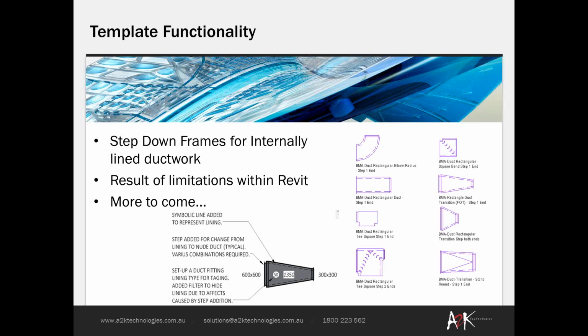Okay. So in conjunction with some of the users involved in the BIM MEP AUS user groups, we've developed these step-down frames that allow you to keep the airway size the same basically, but represent graphically on the screen in the documentation that there is actually a step down there.